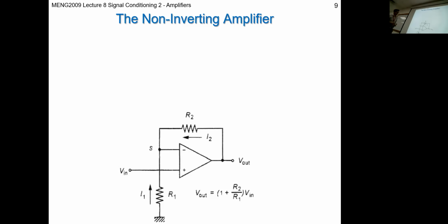What else are we going to get? This is the final result, what we're trying to derive, what we're trying to prove at the bottom here. What else can we say? Well, based on the relationship across these two poles, we know that the input voltage is going to force the voltage at the negative pole to match it. That's another relationship with the op amp: V negative equals V positive. Remember that rule? And the other one, by the way, is I at negative equals 0. There's no current flowing through.